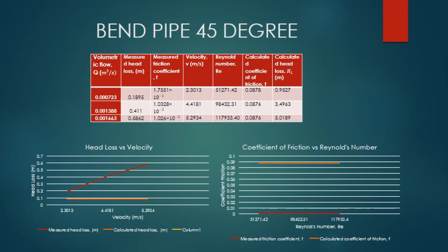So the conclusion that we can make is that we finally reach our lab objective by determining some of the parameters such as head loss by pipe friction coefficient, loss, velocity, Reynolds number, which is clarified by the dynamics of fluid phenomena in pipes. Then we look at the parameters and explain how they apply to the pipe losses.